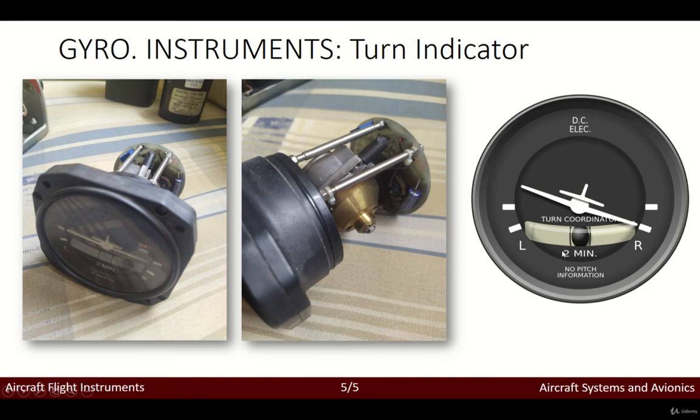Notice also that, in order to coordinate our turn, we can make several indications, such as these two lines, which indicate a 2-minute turn. This is considering that 1 degree can be divided into 60 minutes. So a 2-minute turn would be on this line, over here, which naturally flows from one side to another by changing the roll position.